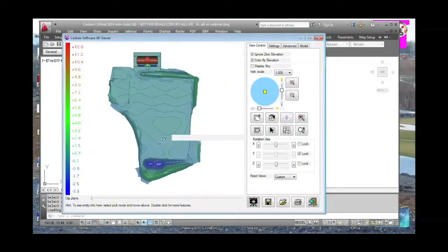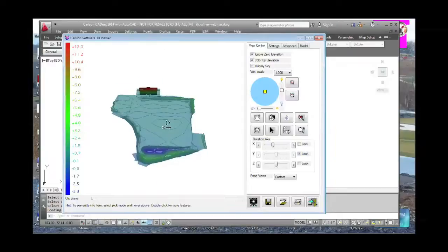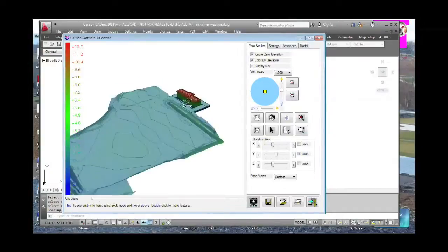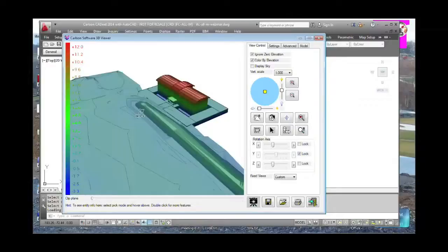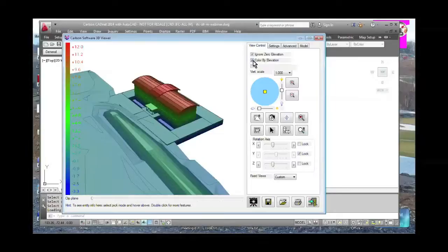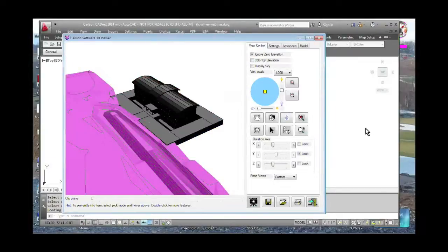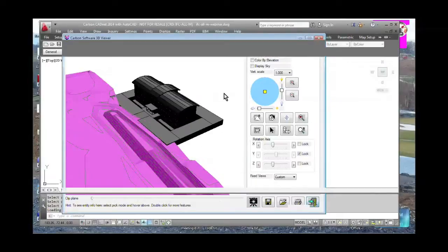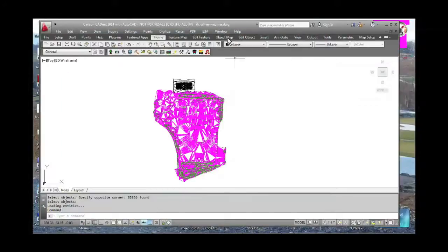Now you'll see the BIM model and my terrain model, and I can see them together, and I can see how they fit. There's a landscape berm in the front of the building. We have detention ponds off in the south, and there's the building itself. I have it colored, which we don't need to do. And so there's your BIM model integrated with the CARLSON data. Okay, and I can see some of our modeling needs to be cleaned up a little bit. There's a little overlap around the sidewalk. Maybe it's intentional, maybe not, but I can visually see that right now. And so that's the idea. I'm doing quality control. When it comes to BIM, this is quality control.